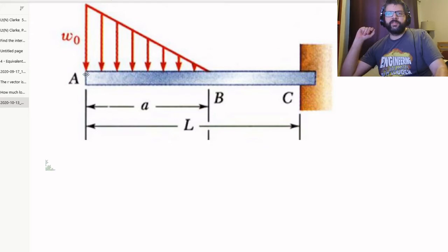Basically, at this free end, we know a couple of things. We know initially there is no shear reaction. There's no reaction there, so there's going to be zero shear at that end until it starts developing due to this distributed load, but at that point it's going to be zero. Same thing for its moment. At the free end of a beam, or at a pinned end of a beam, there is no chance to develop any internal moment, so that is zero at that point as well.